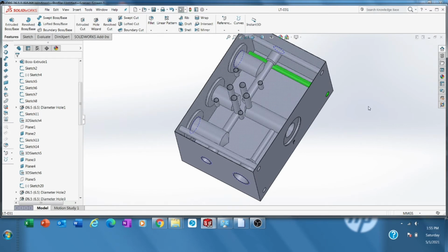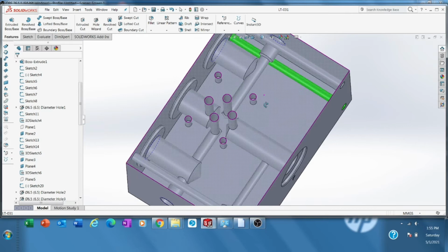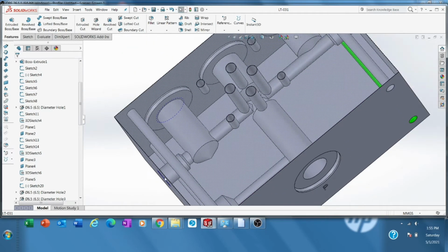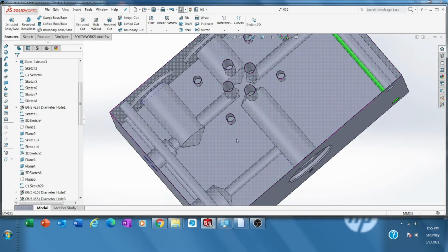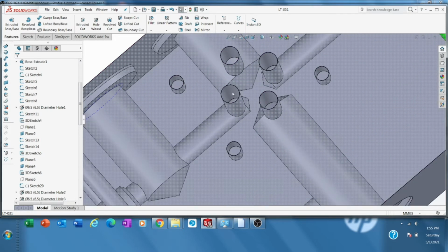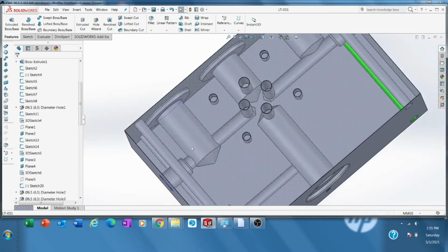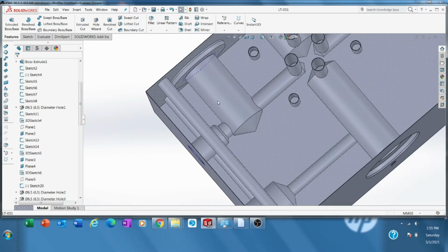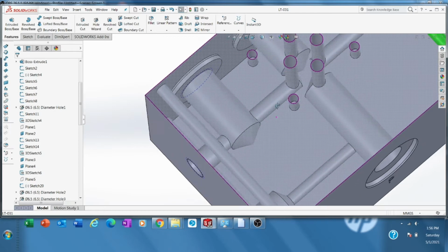It can be done by machining, no need for casting. And as I explained before, why they make a hole here: they have to drill in this direction to have this hole connected to here, and then after that they blind this, because there is no chance to drill from here and suddenly have the tool drill in this direction. There is no technology like that, I think, till right now.